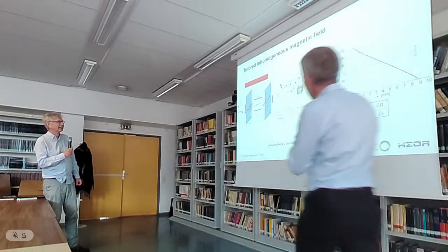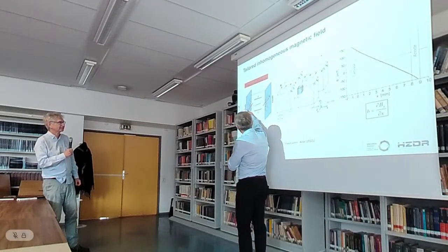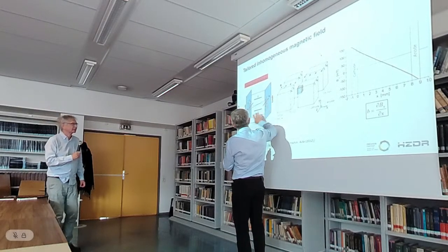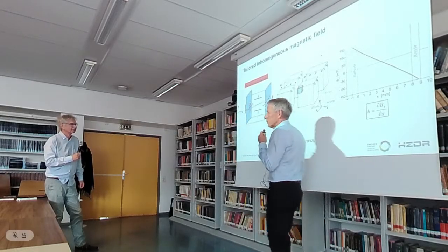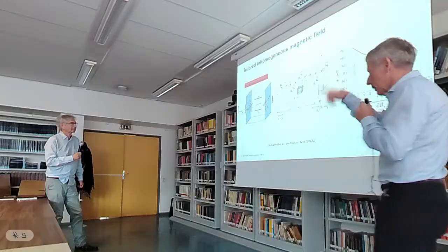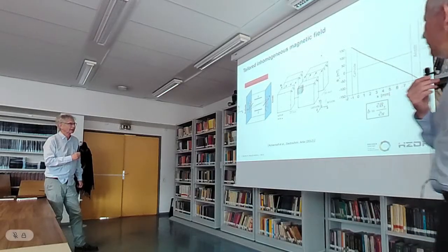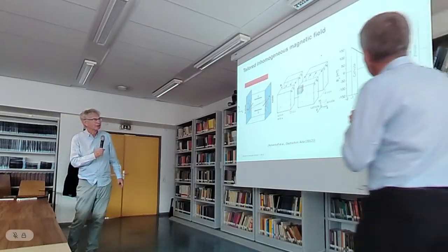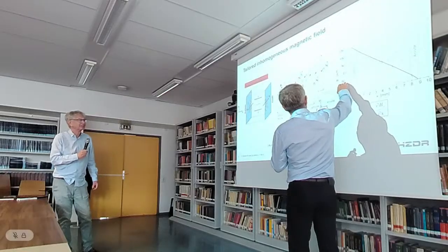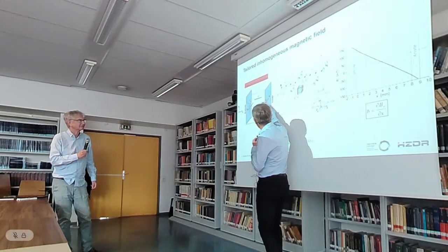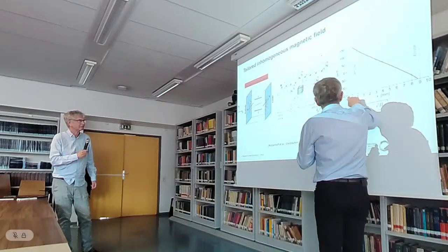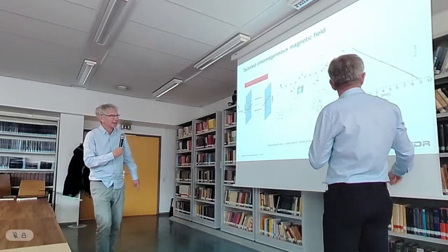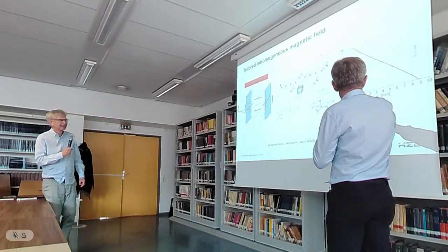Yes, so here it's horizontal magnetic fields which are being directed out of the paper plane into the paper plane, and this gives a supporting stirring at both sides, which then leads to this swirl. Okay, and so this B here is the buoyancy force. No, this is the amplitude of the component of the magnetic field in this horizontal direction versus distance between the electrodes. It shows the small b in the box here. So this is just the gradient.